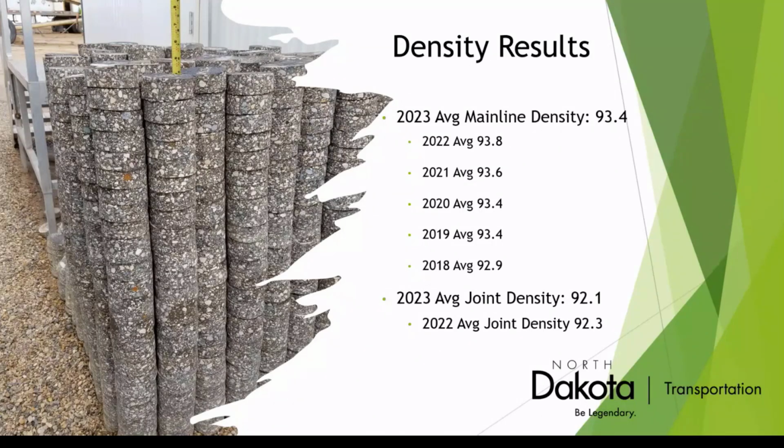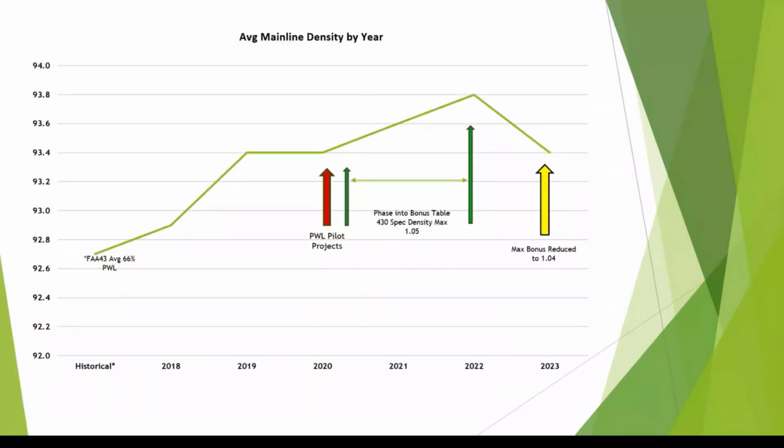And even before all this longitudinal joint density spec came about, North Dakota had changed the standard specifications so that you have to double tack the vertical face. And that was one of the reasons why: if I can close those voids up by double tacking the vertical face, I'm going to get better bond and therefore better density, or fewer air voids in that. So, I put this together based on that previous data you showed.